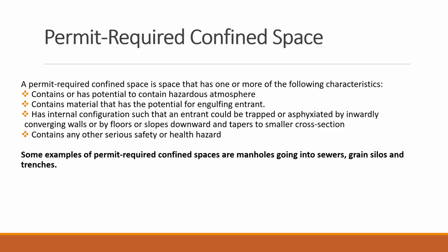If you go to YouTube and search for videos of confined space, you will find many confined space death videos. In a confined space, the major hazard is the atmosphere, because we don't know what's going on inside, right? What are the poisonous gases inside? What is the oxygen level inside? So we need to check it before we enter.